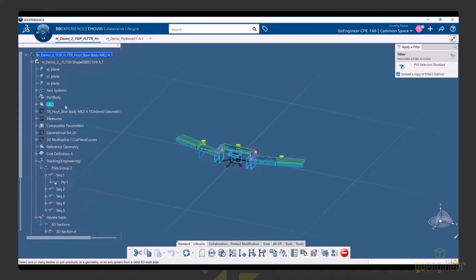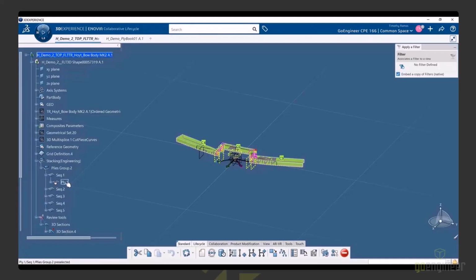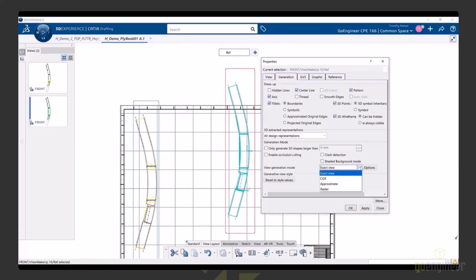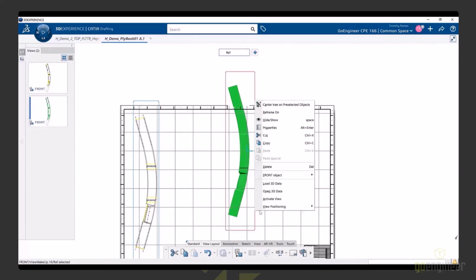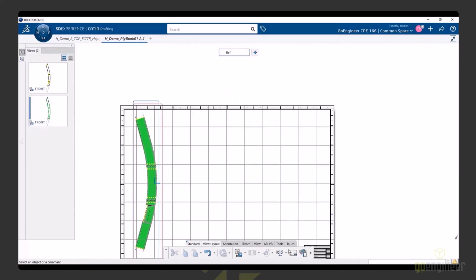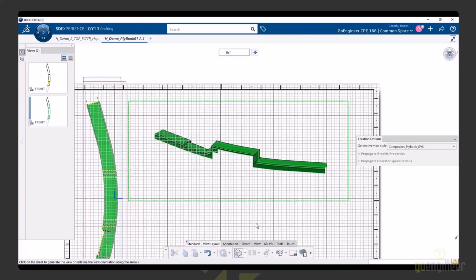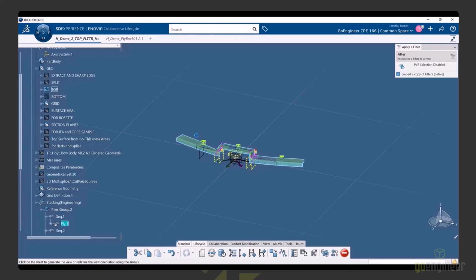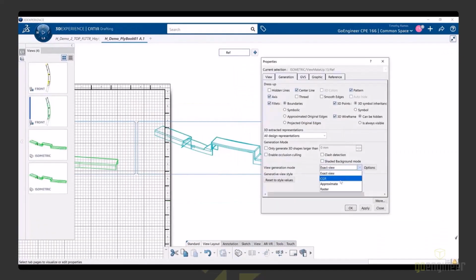Within a ply book, each ply or sequence is assigned to their own drawing sheet. Each drawing sheet shows the individual ply or sequence in manufacturing position, making them ideal for developing manufacturing instruction and standard operating procedures. I will first create the template for how I want each cut piece to be represented in my ply book. For this, I have a top view showing where the ply is applied as it pertains to the mold, and also an isometric view of the ply by itself.